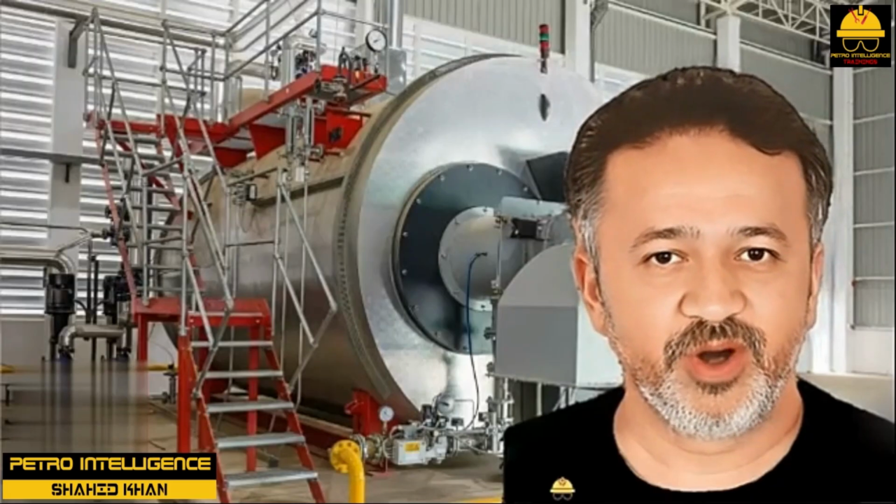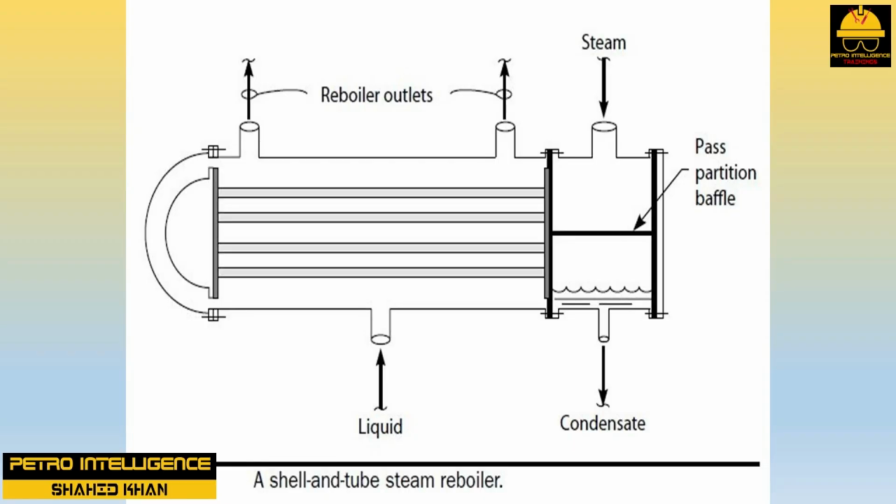Condensing heat transfer rates. When a vapor condenses to a liquid, we say that the latent heat of condensation of the vapor is liberated. In a steam reboiler, this liberated heat is used to reboil the distillation tower. When a vapor, or more commonly a liquid, cools, we say that its sensible heat is reduced. For a small or slight temperature change, the change in latent heat might be large, while the change in sensible heat will be very small.